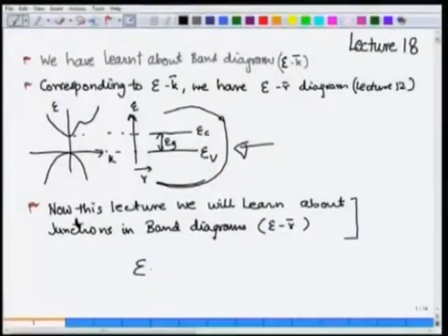You also know we can dope silicon N type, or we can also dope silicon P type. Silicon becomes useful, and we can make devices, if we join this N type semiconductor and P type semiconductor together. Then a junction forms, and it is really the action at this junction which allows us to make devices. So, what is interesting is not the semiconductor material by itself, but some modifications to it in different regions. If we join two materials, then we still need equilibrium band diagrams, and the question we ask is what will be the equilibrium band diagram,